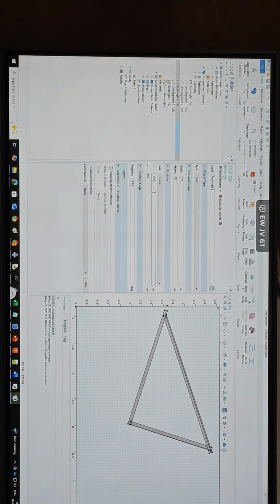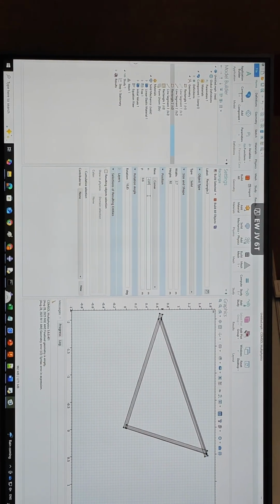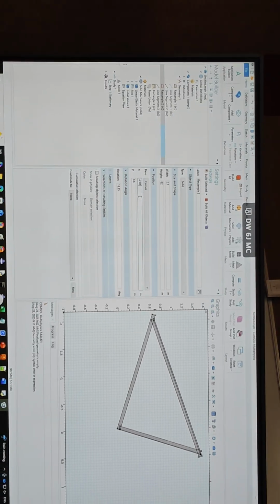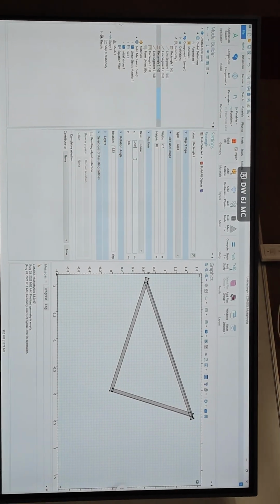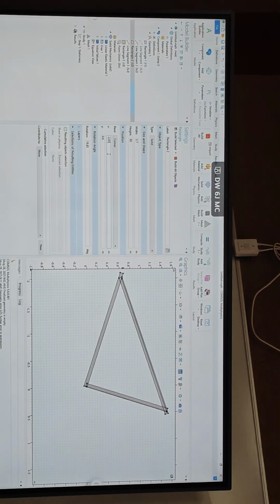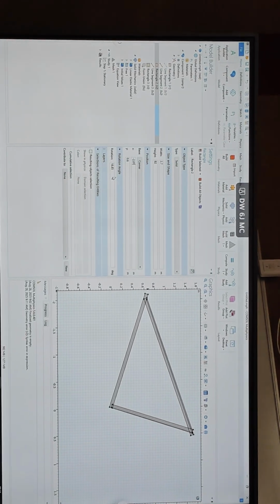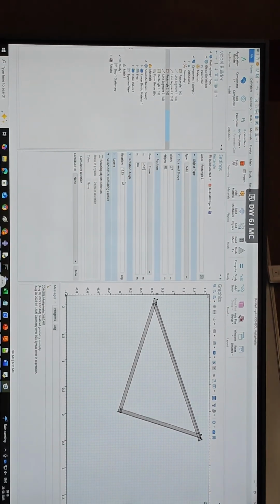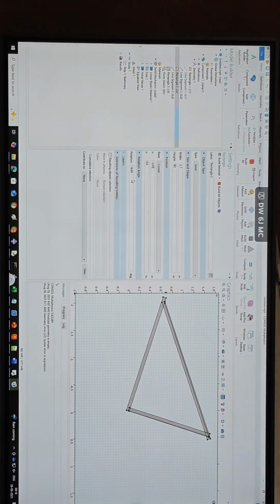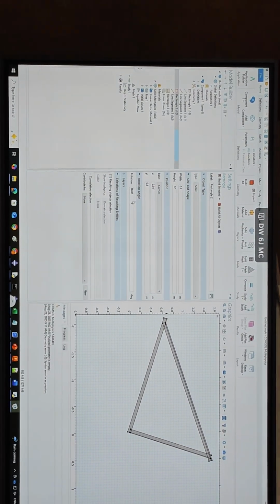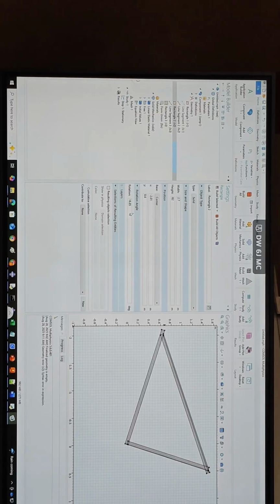So actually the preferable is for the line to be along the center of the beams. You can take a little more effort and place the line along the center of the beam. That is like a neutral axis. You have to play with that, but it's honestly tedious. I'm not going to do that now. The line segment which I'm drawing as a reference should preferably be at the center of this rectangle. Center means it will be the partitioning line, so it divides it into two halves, the neutral line.